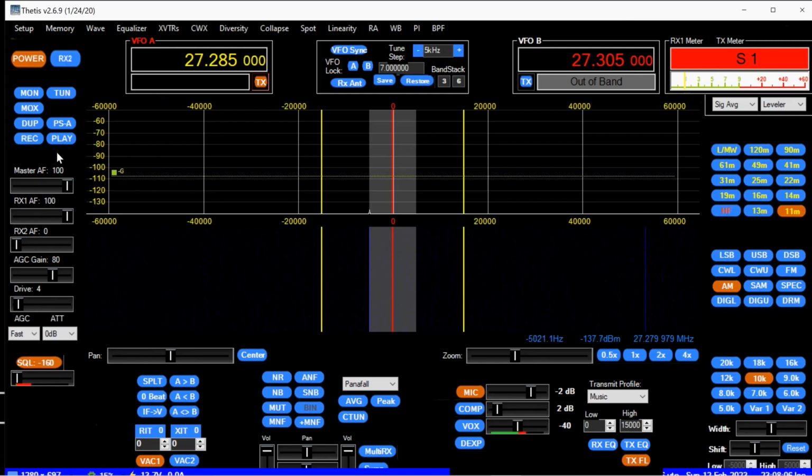Then I'm going to key up and actually transmit. What you're seeing is my transmitter doing its thing, but into a dummy load. I'm going to lower my bandpass filter way down to about 3kc, and during the playback, you're going to hear how that affects the audio. Very low fidelity, and then we're going to work our way up, 3kc to 5kc, like 8, 10, 12, and up to 15kc, and you'll be able to hear at what point we get to the original source sound. I know everybody's ears are different, so it might be at different points for other people. But all right, here we go.